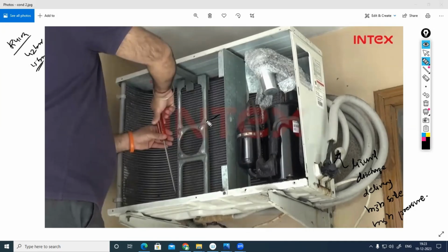Whatever the capacity of the AC machine, it may be 1 ton, 2 ton, 10 ton, the pressure ranges remain the same, but the amount of refrigerant that we are having within the loop, the mass of refrigerant, will increase. Pressure ranges totally depend upon the type of refrigerant only.